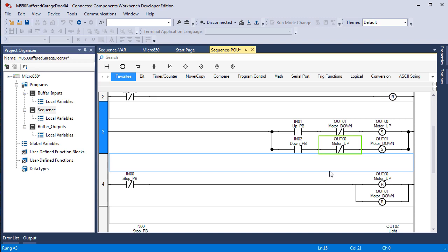You would have to stop it first, and then when you push the stop button, this will go true. This will reset both of these. Now, they're not both set, but it doesn't matter. It just tells both of them you're off. One of them's already off because you can't turn both of them on here. You can't now that we put this in here.